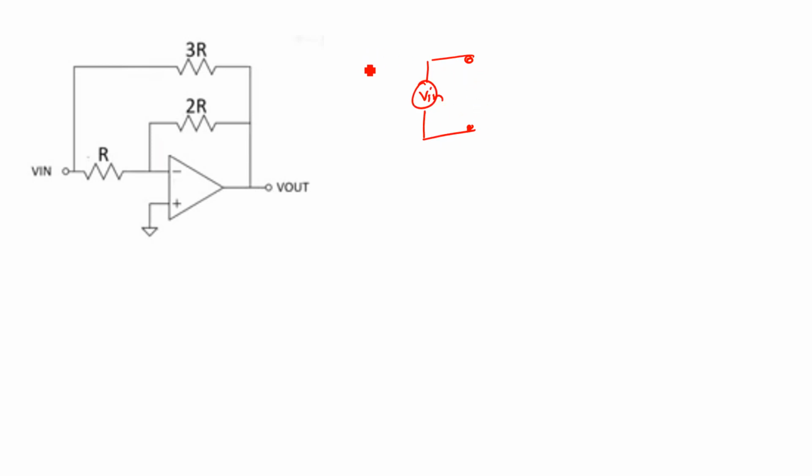You can either take a numerical value like 1 volt, 2 volt, and find the value for the current also, or you can just name it Vin and start solving with the variable itself. So we have voltage source Vin. We put a voltage source across the terminal, and through solving the circuit we find the current which is flowing through the circuit, and let's label it Iin.